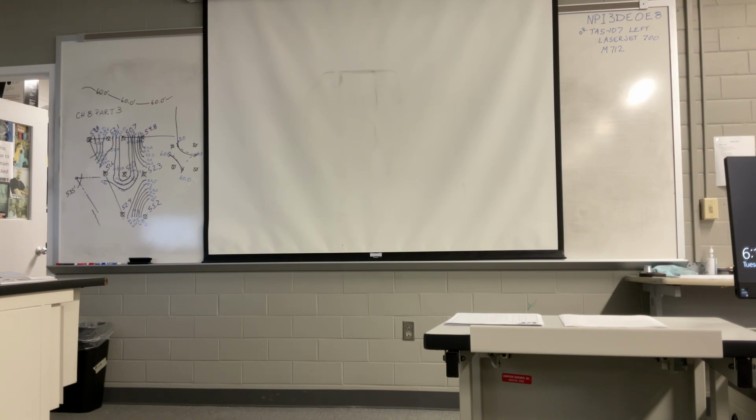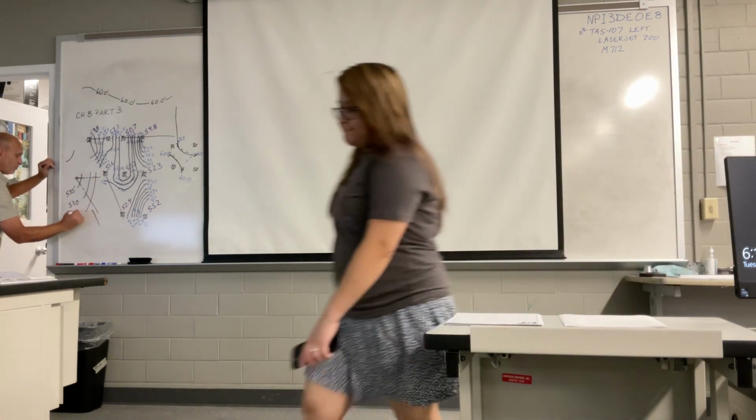But if you come to a contour where you run your contour and it stops out in the middle of your project, you made a mistake. Either you put an incorrect number or you left a number off. Every time, those contours will enter that area and also leave. Either leave by going outside the property or leave by going out another side of that little squared area. But it will work. So on this one, I've got my 53.5, and then I had another contour over here, 53.0. I had another one right here, 52.5.